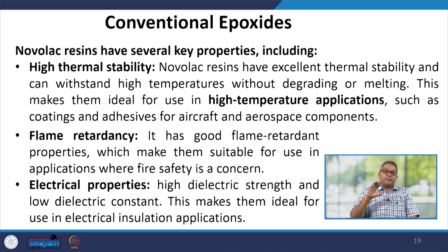This makes them ideal for use in high temperature applications like coatings and adhesives for aircraft and aerospace, and also where there is a wide range of delta T. For example, in aerospace, they may see from minus 38 degrees Celsius to say 47 degrees Celsius. So a lot of thermal stress is involved, which is why they are used in that particular application.